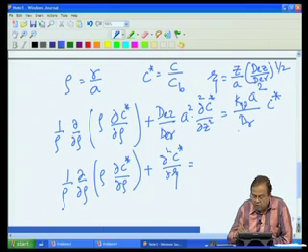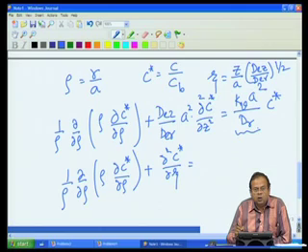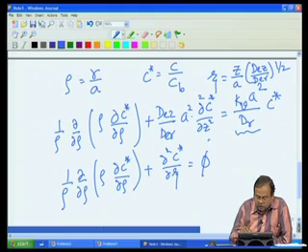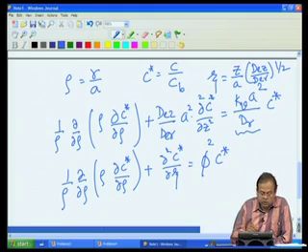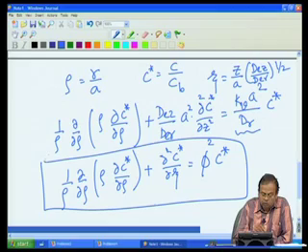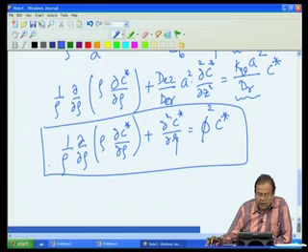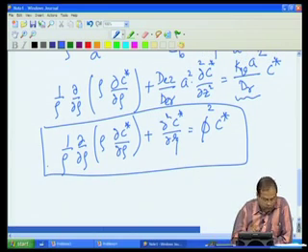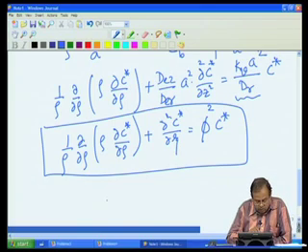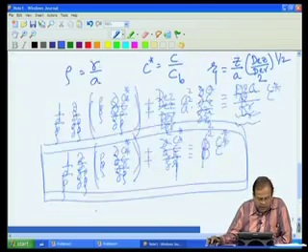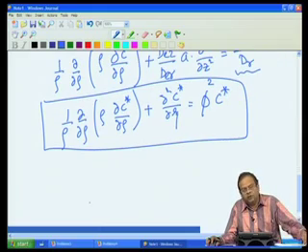Immediately we recognize that this parameter is something which we had done for a first order spherical catalyst, for example, where there was a radius. So, we can define this as a Thiele modulus. It is a dimensionless quantity, phi square C star. So, this is our dimensionless form of the mass balance equation, and then we can similarly convert our boundary conditions also into dimensionless form, and I will skip that part.